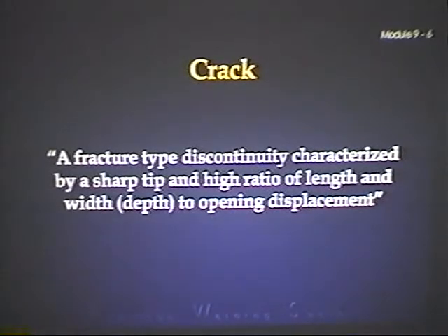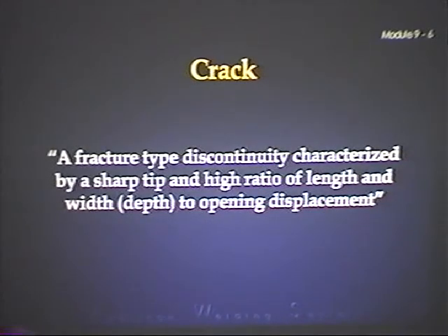Your textbook, I'm going to read from your textbook real quick. Arc strike cracking. Reading from the second paragraph under that subject, it says, when the arc is removed and it is very rapidly cooled again, in effect it is quenched. This affects a relatively small volume of metal, the remainder not being heated appreciably. What they're talking about is when you strike that arc across there, you've heated that base metal right there where that arc strike has been struck, but nowhere else. And because you've struck it right there, you've changed the structure of that steel. You heated it right there, but nowhere else, so it wasn't uniformly heated.